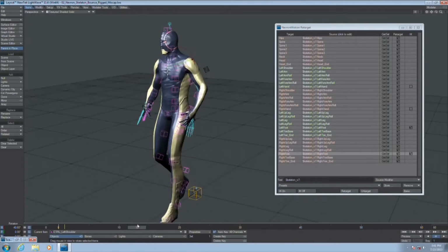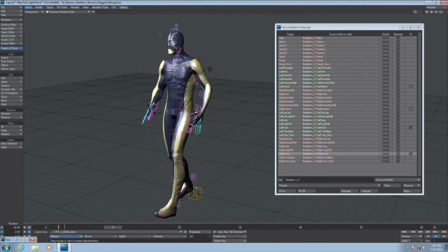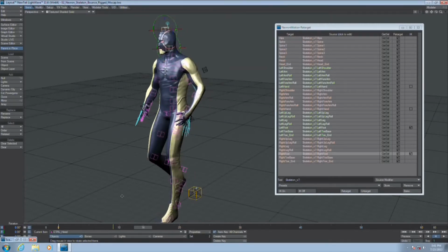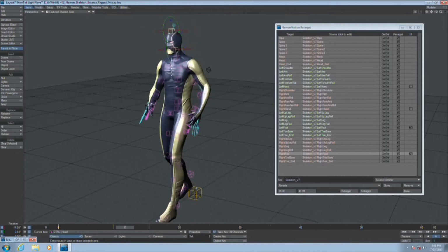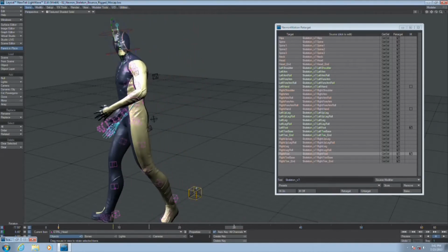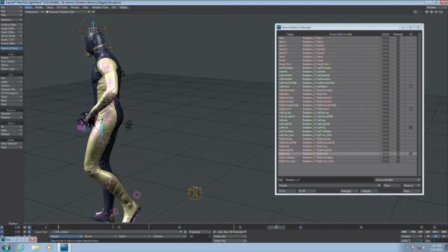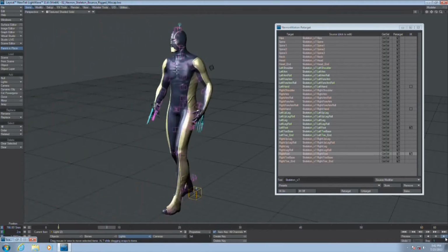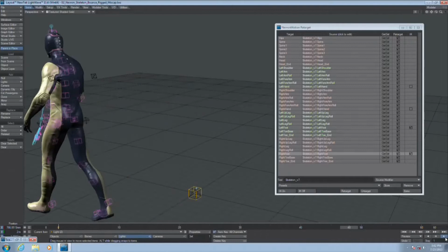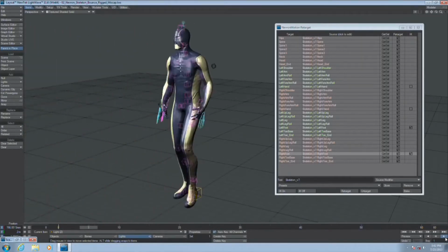Again, let's say this character is looking just straight in front of him. Let's say we want him to look at us. So we can select the head controllers here, create a keyframe, and then just animate the controllers. So now he is looking at us. And finally, we can come back to the original motion capture. So now what's going to happen is that we have this animation. We added something completely new. It wasn't there. We didn't have to go back to the motion capture studio to do that. We can over-animate what we have in the motion capture.